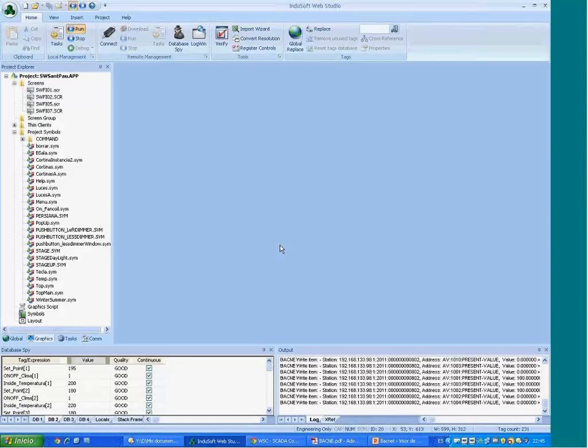As Scott told you, we also have many customers that use InduSoft like a gateway. As InduSoft has a lot of drivers, in the case you need to exchange information between systems where the information is not equivalent. For example, you cannot pass the scheduler you get from BacNet to another system. It's impossible. They will not process that.